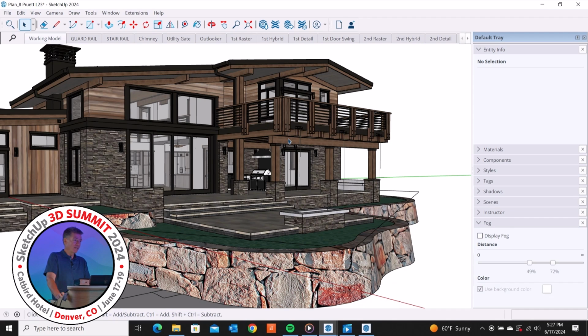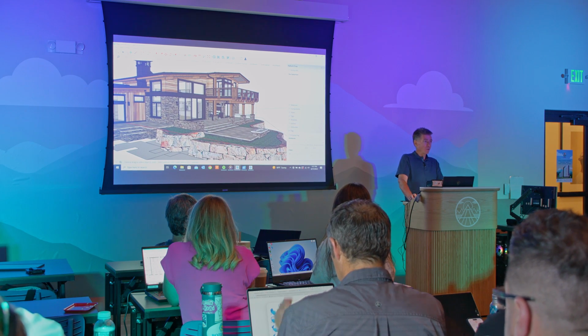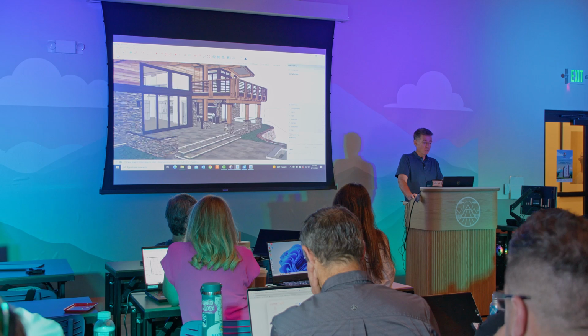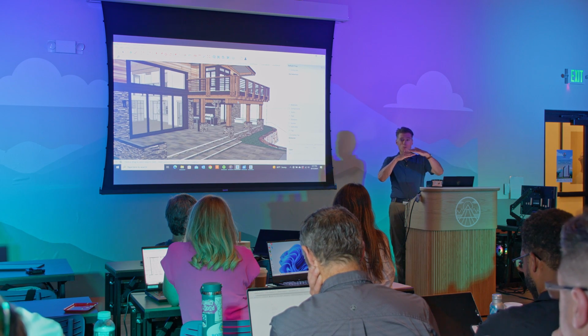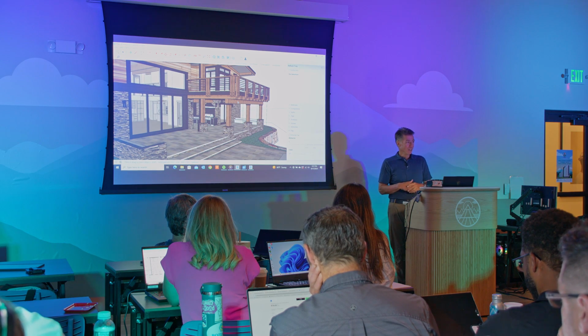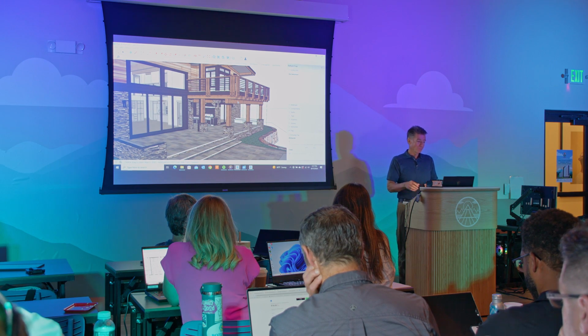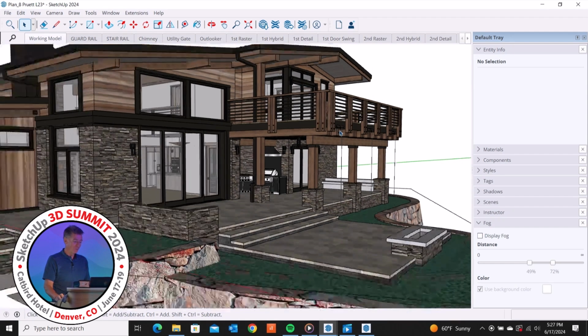And getting it radio frequency dried is really difficult now too. So some contractors are convincing clients to go green. I always caution them because a lot of our connections are knife plates. I've had conditions where the post shrunk from the beam, and you see a gap right through, and that just looks terrible. It's like, get some snow on that thing, load it up.